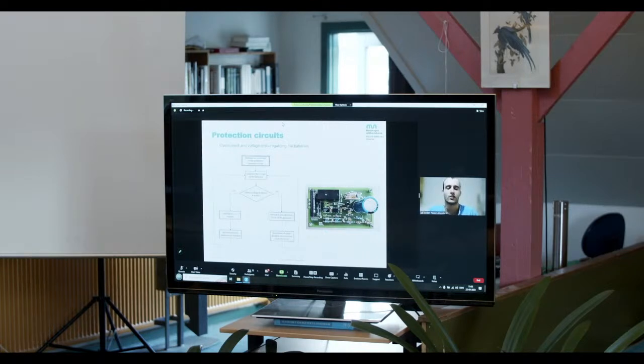Taking into account how the circuit works, we have a diagram here on the left side of the slide. First of all, batteries must be connected to the electronic circuit, and then the voltage they have is supervised. If the voltage is in the range AB, what does this range mean? It is the range where the optimum charge of the battery happens. It is called this way because as we have 3 different boards, if numerical values were put here, it wouldn't be so understandable. So if we are inside this efficient charge range, the generator is not braked and normal operation happens, which means that batteries are charged.